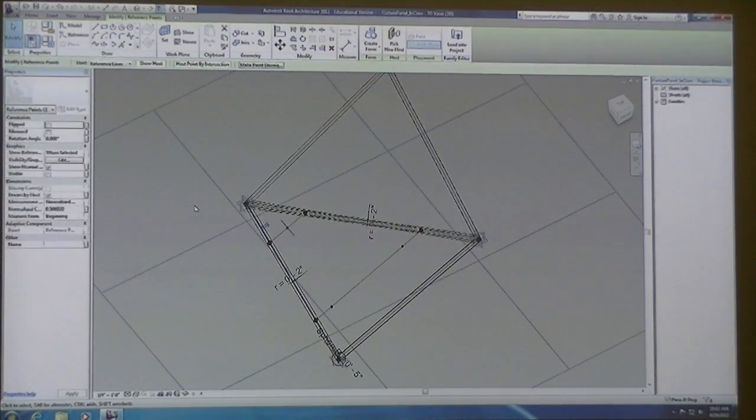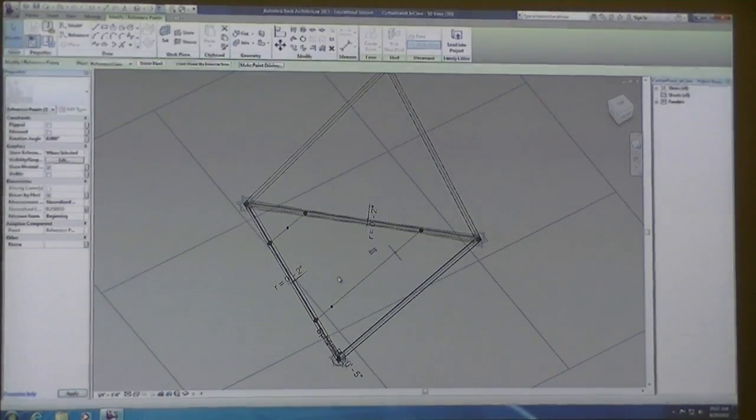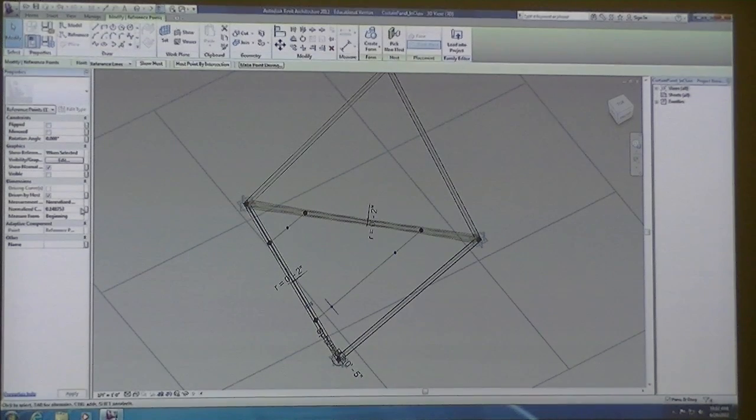If I snap to the midpoint correctly, if you click on that point, it should be equal to 0.5 as your normalized curve parameter. Then these other points that are down here, I'm going to make those equal to those same parameters that we already set up. If I click on this point and it's greater than 0.5, I'm going to make this the void offset inverse. I'm going to do the same with the other one.